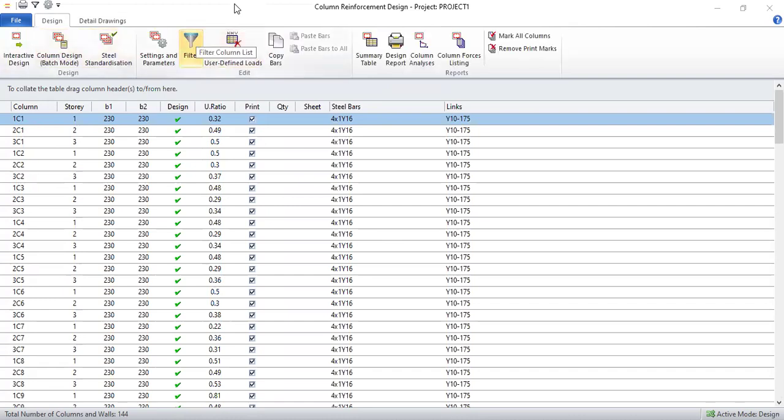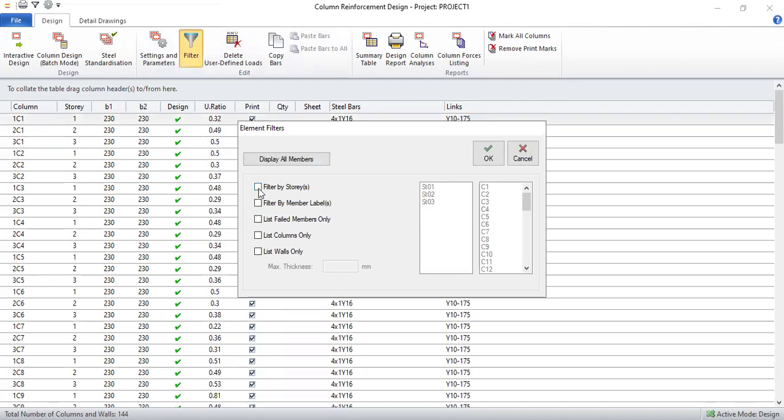This we have done with the modeling. We have done with the analysis now. Analysis is okay, meaning analysis is passed. What we need to do now, you go to design. The design means that each of the columns that are supposed to be Y20 or beams that are supposed to be Y16, how many top bars, how many bottom bars. This is the design. On these columns, you can filter, go to story 1.